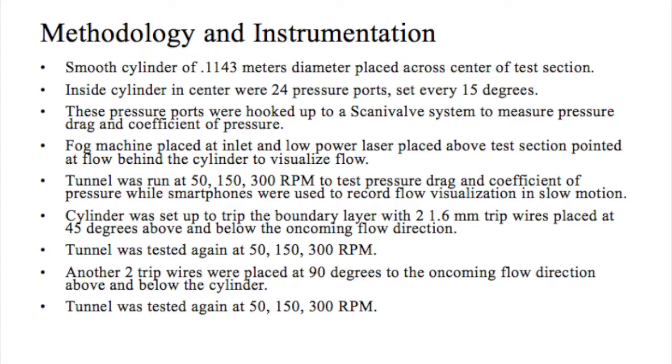Before any testing was done, the safety working procedure was gone through. We made sure there was a supervisor around to keep things under control, opened the garage door behind the diffuser, checked around the tunnel for loose items that could potentially become hazardous, closed the doors to the wind tunnel area, and put up red flashing lights to warn people outside that the test was about to be done.